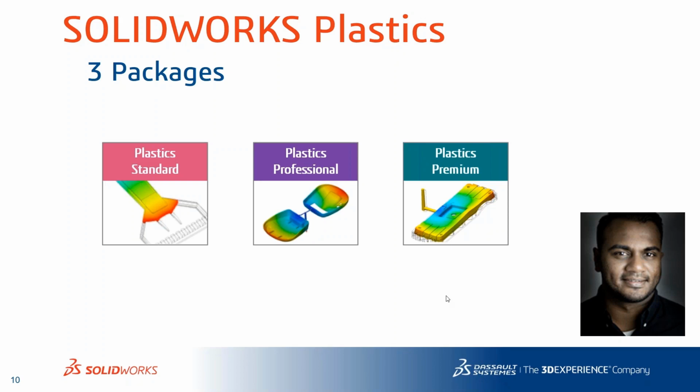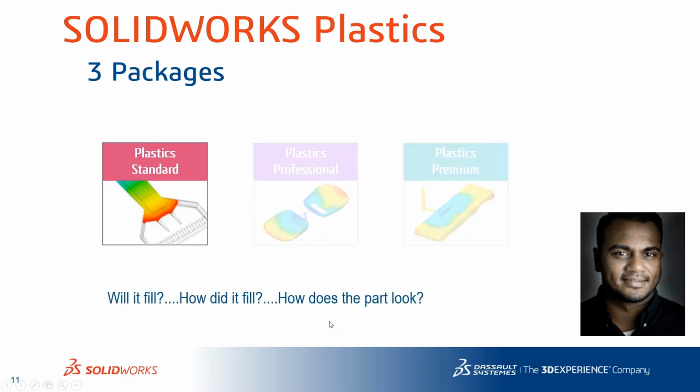Thanks, Bob. Wow, that was quite the adventure that you had there with that plastic part. A lot of that could have been avoided by implementing simulation into the design phase, which is so important these days that it just has to be a part of designing a part. And beyond that, with some of the things that you did in the first webinar, you talked about, will the part fill? How did it fill? You might run into some race tracking issues that could cause weld lines.